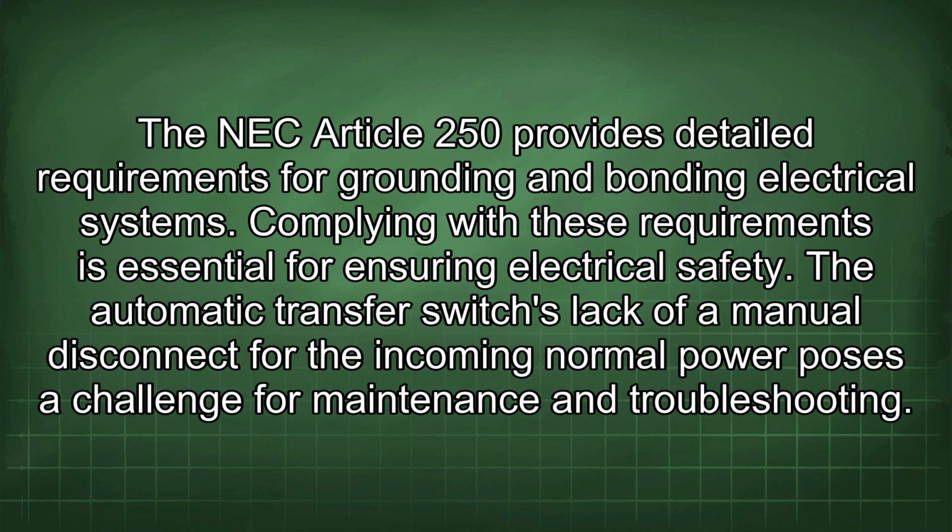The NEC Article 250 provides detailed requirements for grounding and bonding electrical systems. Complying with these requirements is essential for ensuring electrical safety. The automatic transfer switch's lack of a manual disconnect for the incoming normal power poses a challenge for maintenance and troubleshooting.